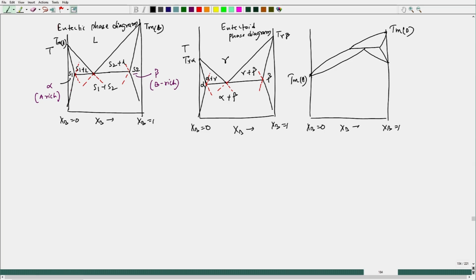These are the equilibrium transformation for the pure metals. Now, this is delta plus liquid, this is delta plus gamma, this is delta, let us say this is liquid plus gamma, this is gamma. Now, if I try to extend the stable composition into metastability, this is extended like this, this one is extended like this, and this one is extending like this. If you follow this up with the free energy composition diagram, you will get all those dotted lines, those are the metastable lines.